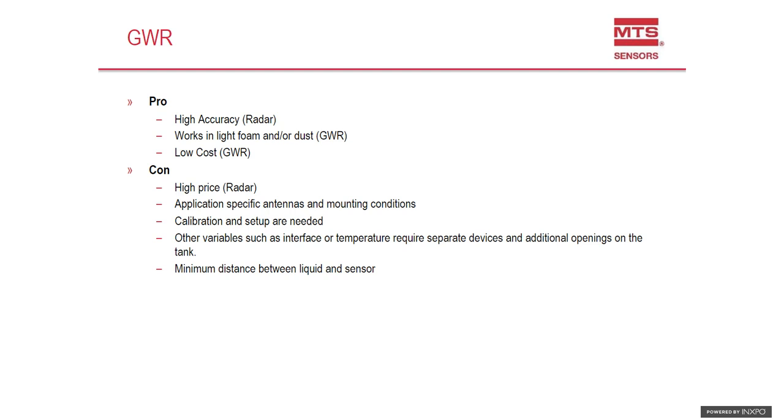You do have a lot of specifics around the mounting of these units, where it's mounted, how it's mounted, the angle at which it's mounted. The other part of it is you do have to do a lot of calibration and setup, especially for the guided wave radars. If you purchase one of the units that can be cut to length, then you end up having to do the calibration in the field. So mechanically you're able to cut it to the length of the tank, but then you do need to go in and work on the electronics to make sure that you have it tuned for that specific application.